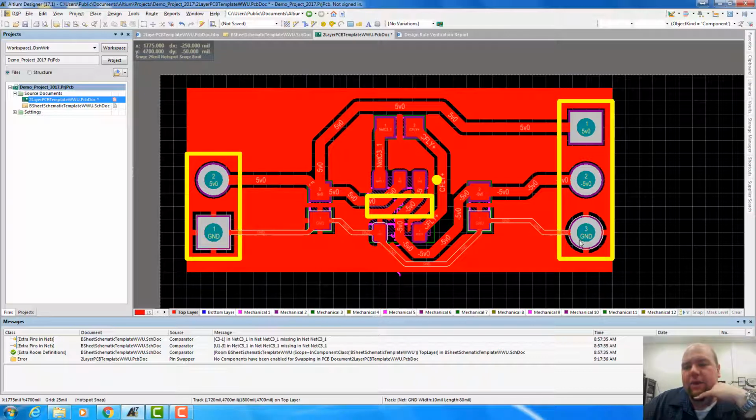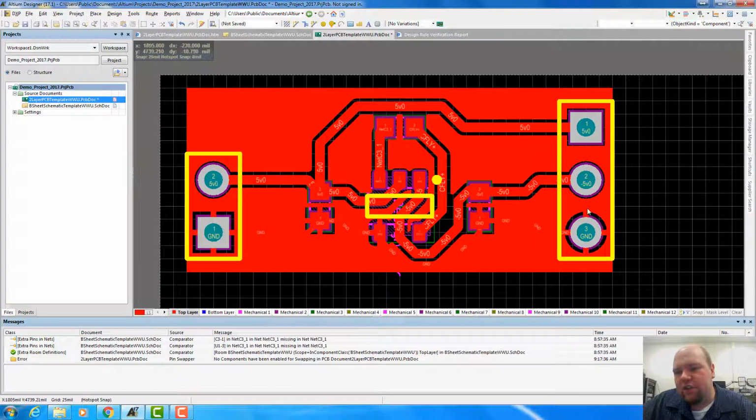If your board is cold, it can be very difficult to solder a part onto a ground plane because that ground plane is so good at sucking heat away from the tip of your soldering iron. So in this case, it does these thermal reliefs, which still give you good electrical conduction, right? These are very short, so there's still fairly low resistance. But it also gives you good thermal insulation, so you can actually solder to these things.